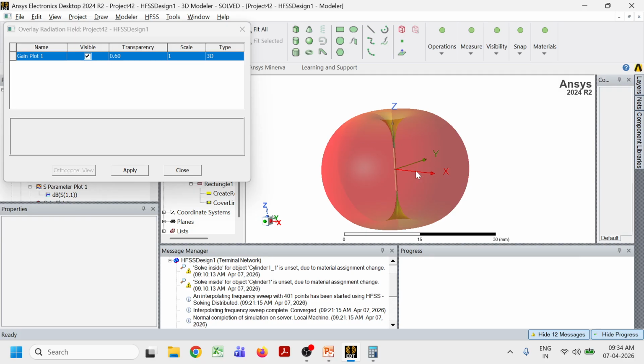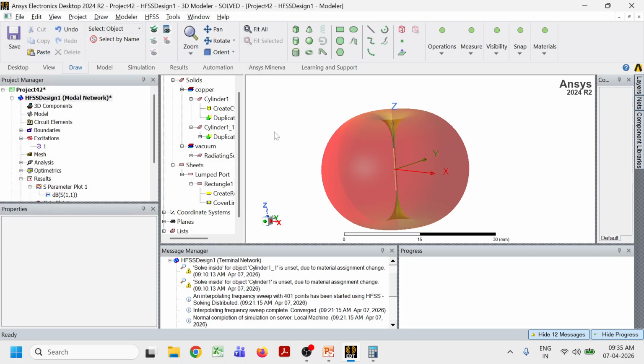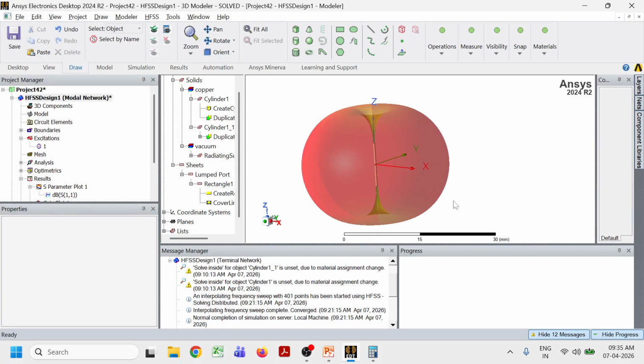So most of the antennas where we need horizontal direction, it should be propagating in all the horizontal directions. We will prefer either a monopole or a dipole antenna or its variants, for its omnidirectional properties, meaning it will be able to receive the signal from all the directions. At the same time, as a transmitter, it will transmit the signal in all the directions in the horizontal plane. That is the property of this dipole antenna.